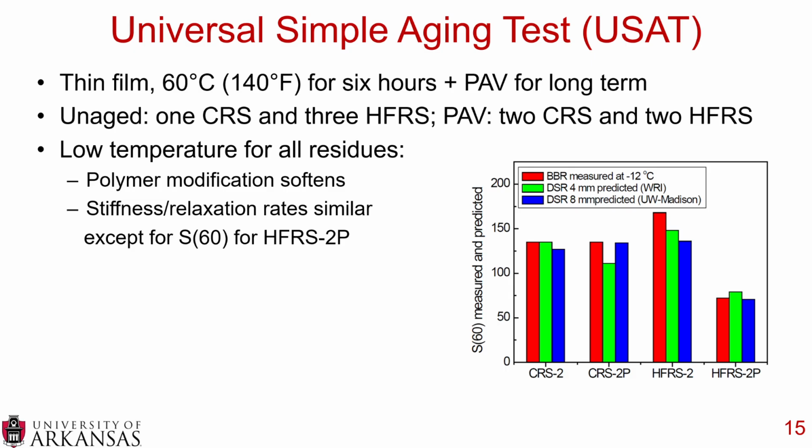And now this is at low temperature. Remember, I talked quite a bit about how, in theory, high float shouldn't impact low temperature performance. It only impacts the high temperature. But here we may be seeing something a little different, and that's definitely something worth looking into. And this can be helpful for the traditional chip seals in low temperature environments, keeping that aggregate retention, especially with snowplow damage.